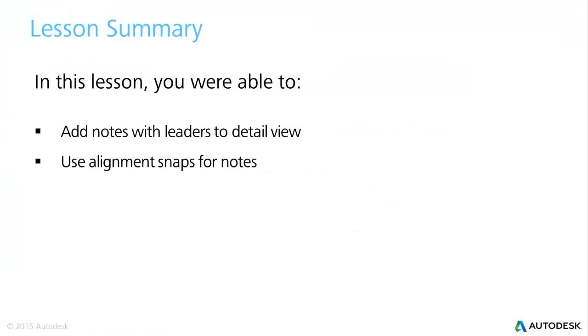Let's review the learning objectives for video 7. In this lesson, you were able to add text notes with leaders to an elevation view. And then to keep those lined up, we used alignment snaps. And we also learned how to create notes with 2 lines or multiple lines.